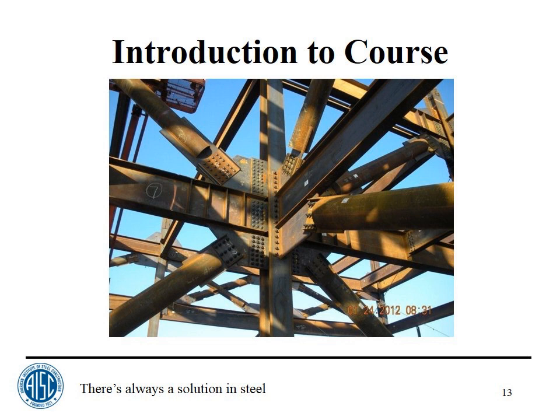Well, I think that generally for horizontal braces, we're talking about a wraparound gusset, and the distribution of forces is just a lot simpler than that kind of connection. And usually, you're not really worried about the connection of one beam to another beam, but there's no reason why it couldn't be used. If you had, say, one beam running through a joint and the other beam stopping, then you could say that what I'm calling the other beam is the beam, and the continuous beam is the column. And you could use the uniform force method there. There's absolutely no reason why it couldn't be used. You could use the KISS method, too, if you want to.